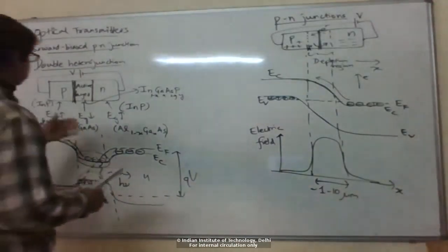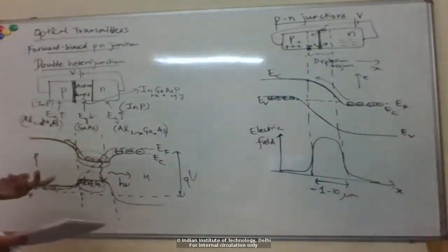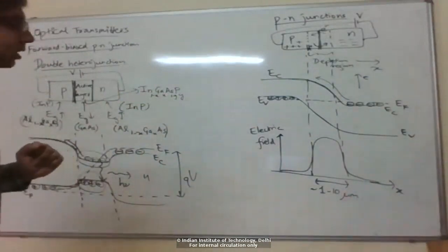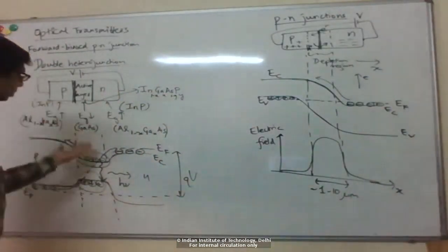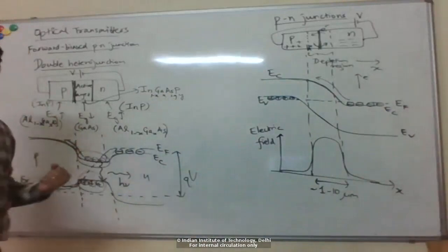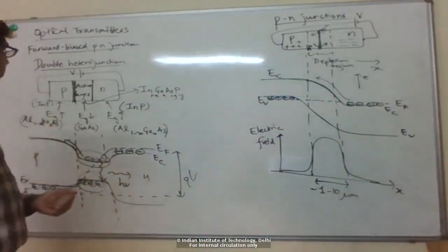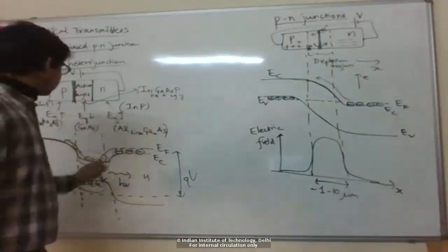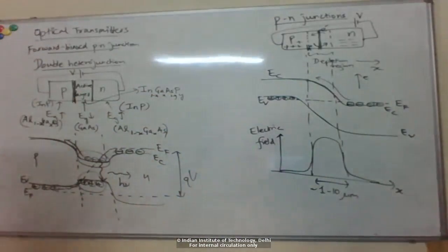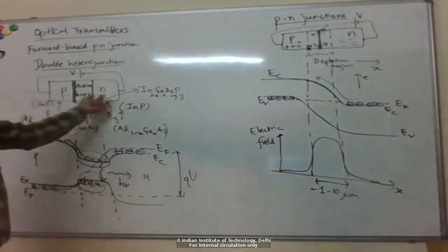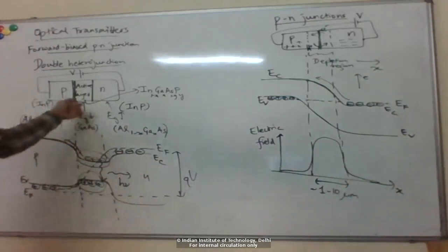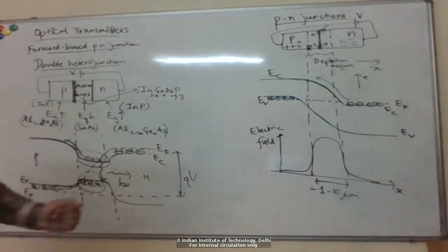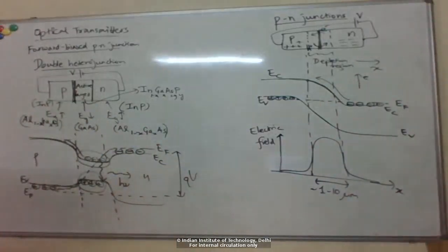Okay, so basically this sort of capability of changing the band gap by just controlling the atomic mole fraction was really helpful in making, first of all, these double heterojunction devices, which were much more efficient than the homojunction, and also in controlling the wavelength, right? So by controlling the band gap of the active layer, I can use the same substrate, for example, and grow different active layers in different regions of the chip and have different wavelengths emitted, right? So it's a really versatile technology.